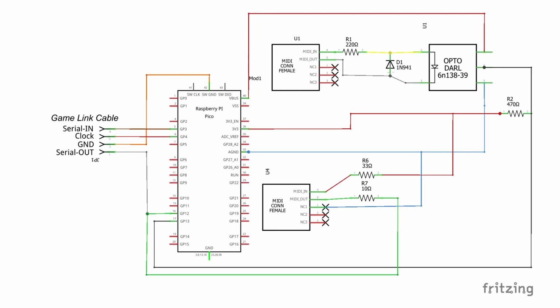In truth, the multi-interface link approach to 16-channel MIDI playback on 4 Game Boys is actually rather simple. Since my previously developed MahPicoBoi already introduced an algorithm to send out all 16 MIDI channels via the GPIO pins GP3 and GP4, all we'll need to do now is to define 6 new GPIO pins that will be used to transmit the isolated signals to the 3 new Game Boys of our system.